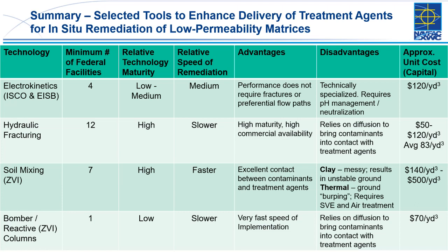For thermal, when we're injecting steam, it has been known to result in what's been described as soil burping, which needs to be monitored, managed, and designed for. It also can be very expensive, but on the bright side, you're in and done, and there is no long-term O&M.